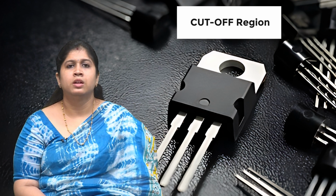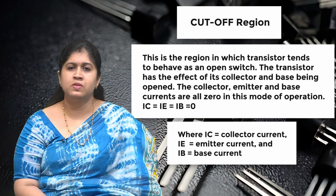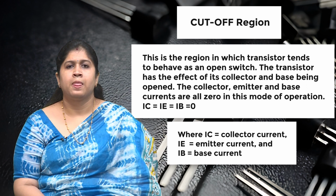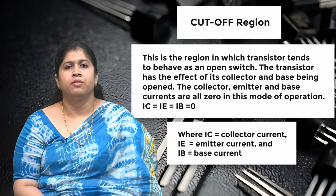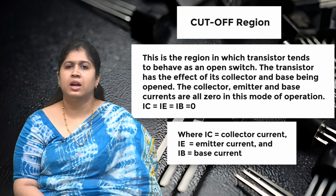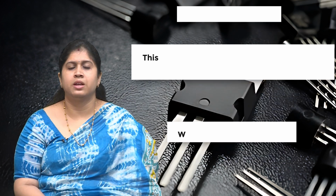Cutoff region. This is the region in which the transistor tends to behave as an open switch. The transistor has the effect of collector and base being open. The collector, emitter and base currents are all 0 in this mode of operation, where IC equals IE equals IB equals 0. IC is the collector current, IE the emitter current and IB the base current.